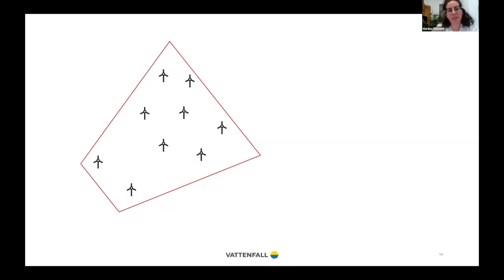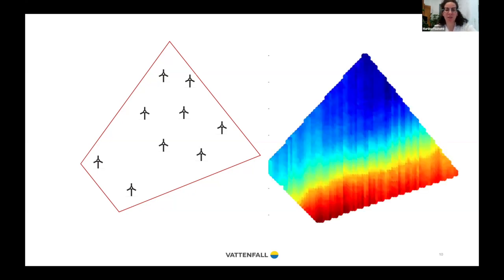And then for deciding how to reduce the cost, they were basically analyzing the cost of building each specific turbine in the layout selected and then moving them manually. We instead wanted to insert this immediately in the optimization. And so we proposed to the company, if you could give us a cost map that represents basically for each possible position what would be the cost of building a turbine there, we can incorporate this explicitly in the optimization. And as we will see later in the results, this also has a significant impact.